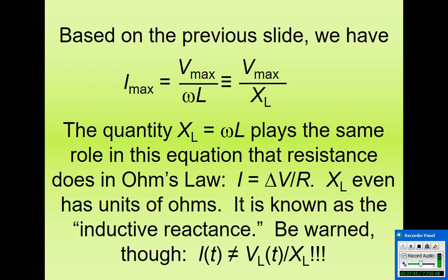But once again, like with capacitive reactance, it only allows us to determine the amplitude of the current compared to the amplitude of the voltage. It is not going to tell us the current at all times if we know the voltage at all times.